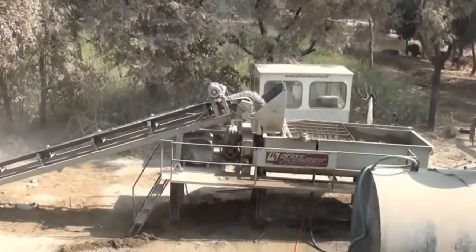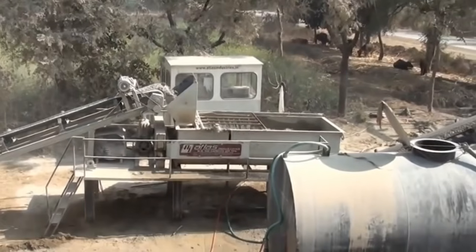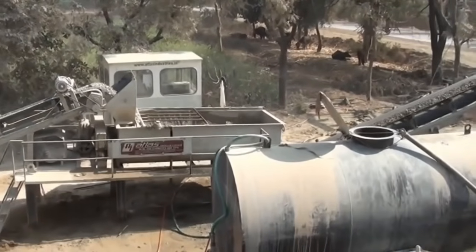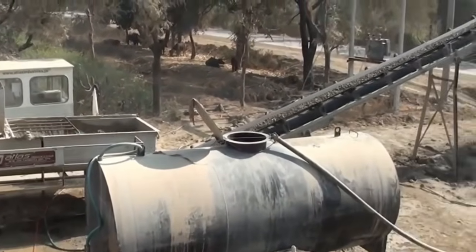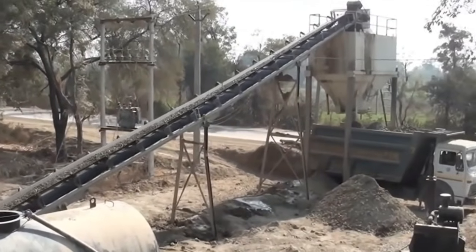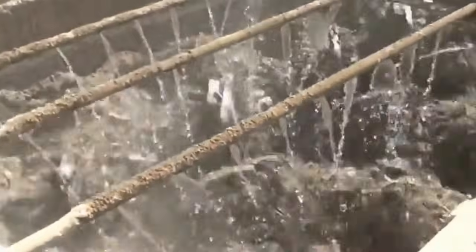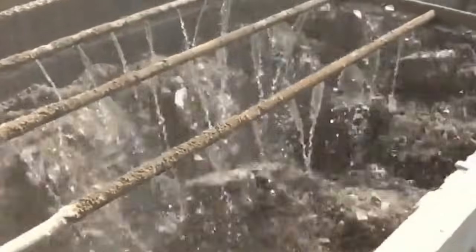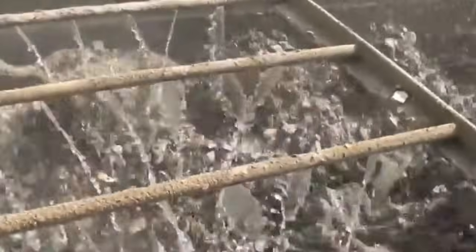Wetmix Macadam shall be prepared, as per approved proportion of aggregates, in the pug mill plant with controlled addition of water. Water is to be maintained within the limit. Generally, 1 to 2% extra over the OMC shall be maintained in the mix, to compensate for evaporation losses, depending upon the lead and season. The mix shall be transported from the plant to the laying site. If the existing subbase surface is found to be dry, water shall be sprinkled before laying the wet mix.